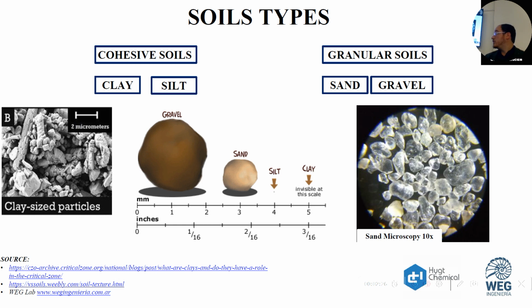This is the approach we took because we were working on cohesive soils, and we found out that the chemicals produced for stabilization of cohesive soils do not fit well in granular soils because the physics behind it is different. So we started from a kind of phenomenological approach, and we said we have to think about the problem differently.